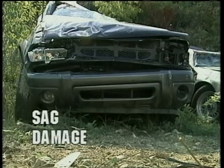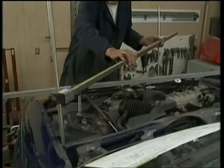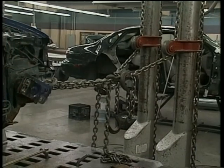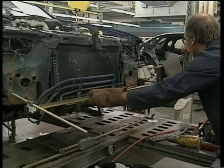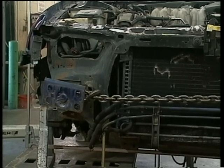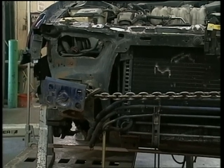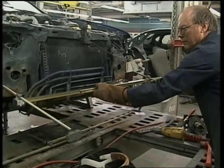To recap, there are 5 basic types of frame damage: side sway, sag, diamond, twist, and mash. After careful measurement, major frame alignment can be accomplished on a rack. Remember, safety first. When pulling, take your time. Make sure all chains, clamps, and bolts involved in pulling are properly secured. Most frame straightening will be accomplished in multiple pulls and require measurements and corrections after each pull.